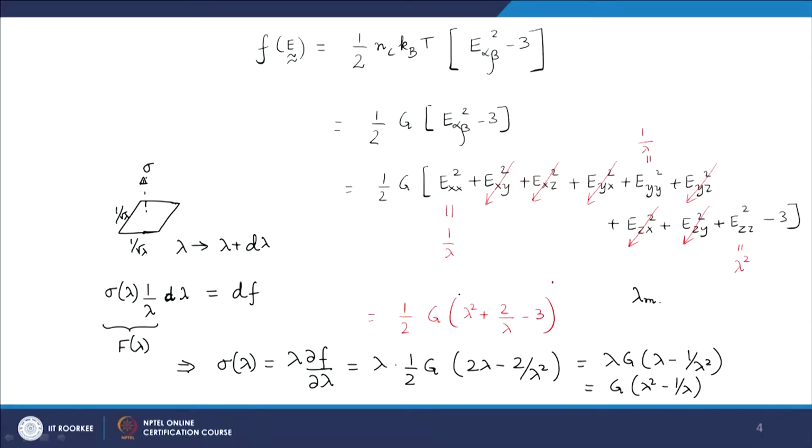So, in reality, there is a limit on the maximum stretching that can be given by the ratio of the maximum possible contour length of a chain or a strand in this case multiplied by the average length for an ideal chain, and this is given by square root of n.